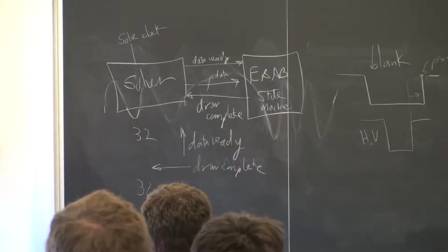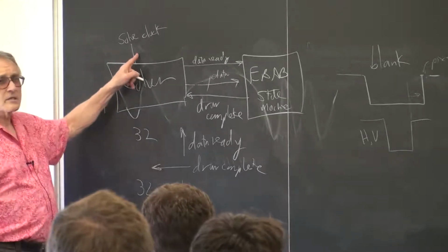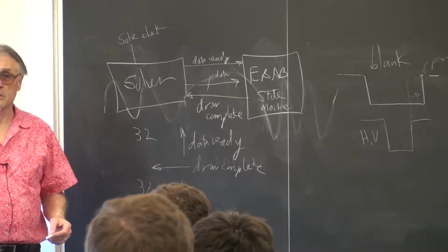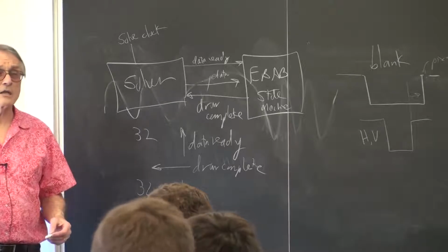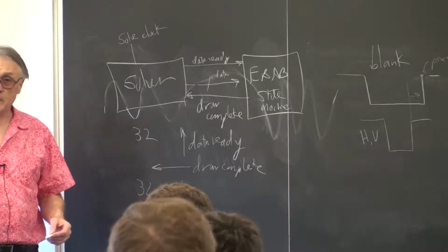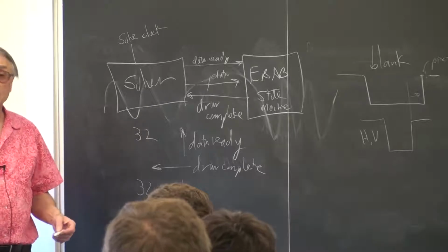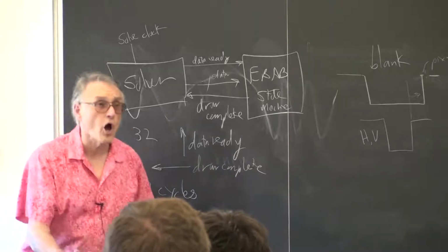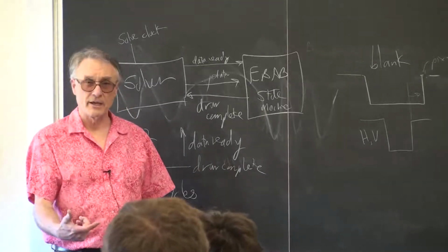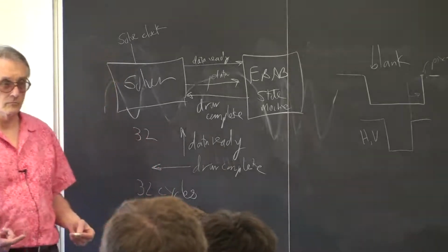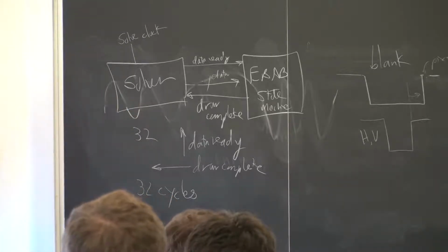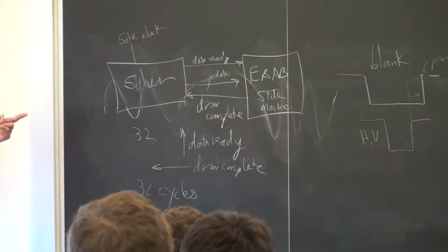Another possibility is to synchronize the solve clock with the H-sync, so that you only clock the solver at the horizontal sync rate, so you're guaranteed to get exactly one solution point per horizontal clock. And since you can always draw during the horizontal clock, you will stay in phase. I kind of like this method better. It's kind of more straightforward in some ways. Has anybody implemented this?